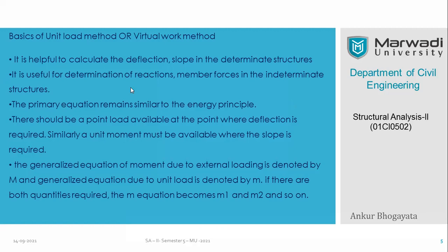So let's very quickly go through some of the salient points of this method itself. It is helpful to calculate the deflection and slope in determinate structures. It is useful for determination of the reactions and member forces. You know that once you have the reactions, you can definitely use the first principles of mechanics of solids, and you can obtain the internal forces like moment and shear force of the structure. One more point I would like to highlight here is you can not only use it for determinate structures, but equally you can use it for indeterminate structures.